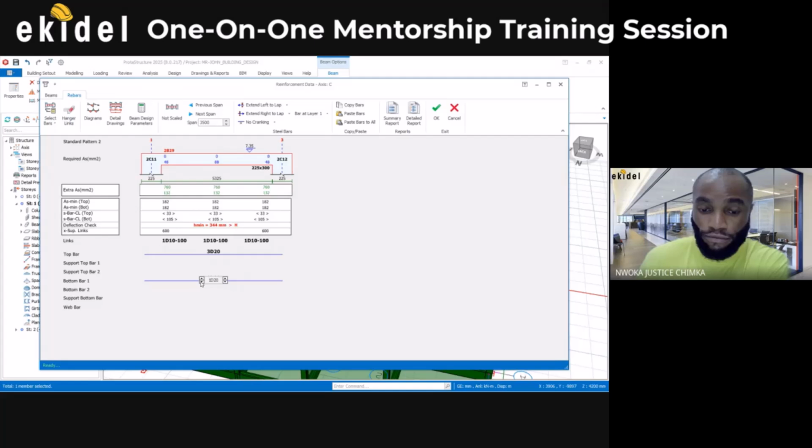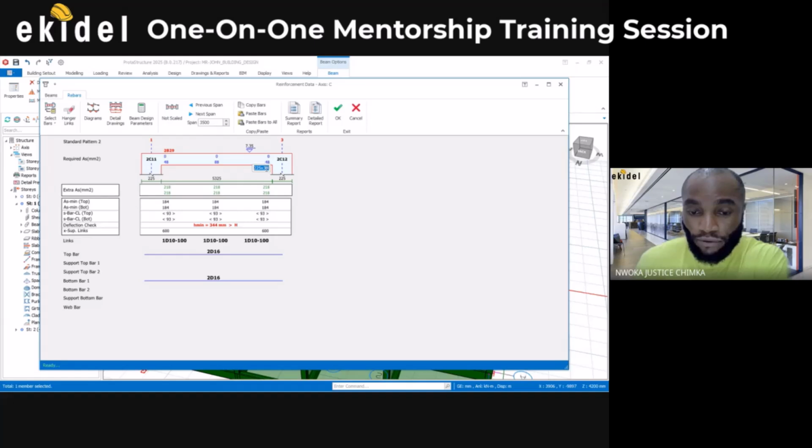So this is not, let me just go back to 2016. Reduce this back to this. So now, for it to apply, like I said, this depth is failing. I know that. So you can come here, under this bin, see there is this new version. Click on this place here, under this depth, and then type in the new depth by just highlighting here. And type, let's say 350 now, and press the enter key.